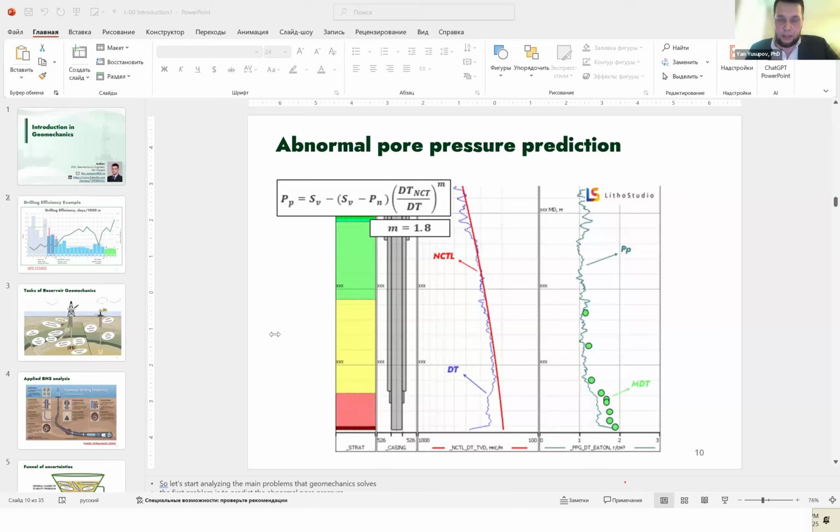How can we develop CCS in the geomechanical analysis? We can make a 4D geomechanical model and estimate the condition of CCS. For example, we can model the injection rate of CCS. We can model the strengths and elastic properties of the seal and reservoir and estimate the uplift during the CCS. We can estimate potential for fault reactivation, DFN reactivation, and other processes.